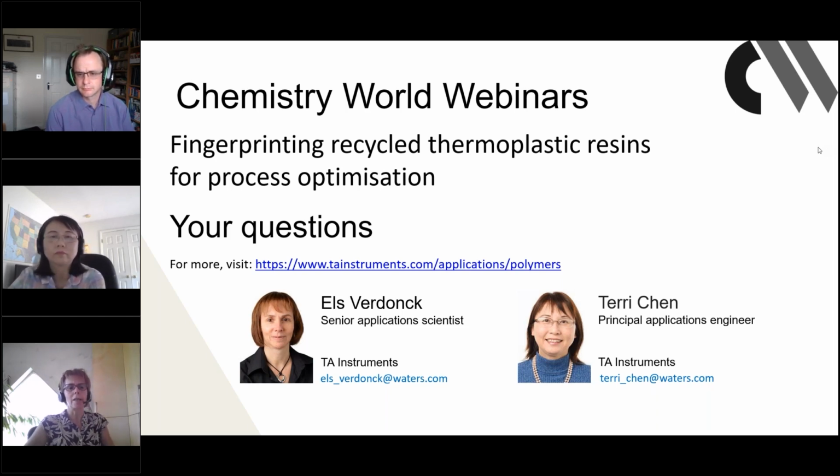Or in case that your contamination is showing a heat flow effect, can be a melting point or a phase transition or whatever heat flow effect it's going to show, then you can measure it with the DSC up to 700 degrees typically. But if your contamination would show some heat flow effect at higher temperature, with a combined DSC TGA, you could even go to 1500 to try and detect it. Great. I think that answers that really nicely.